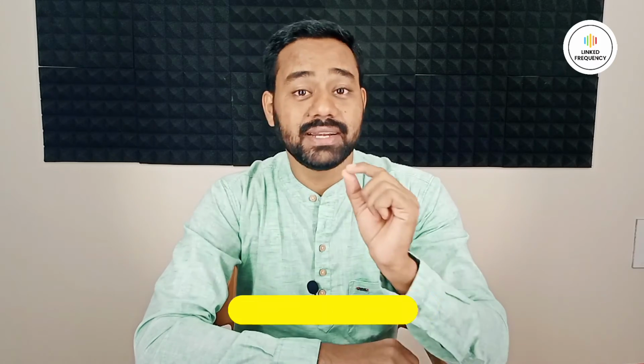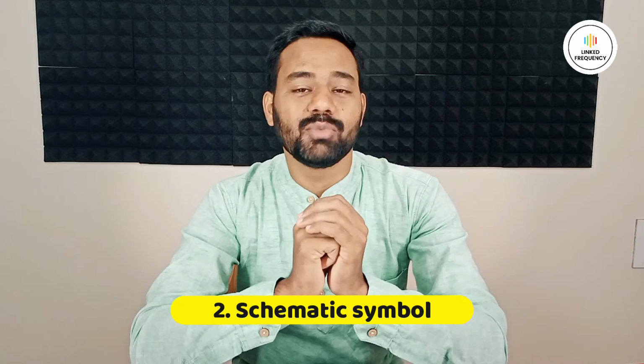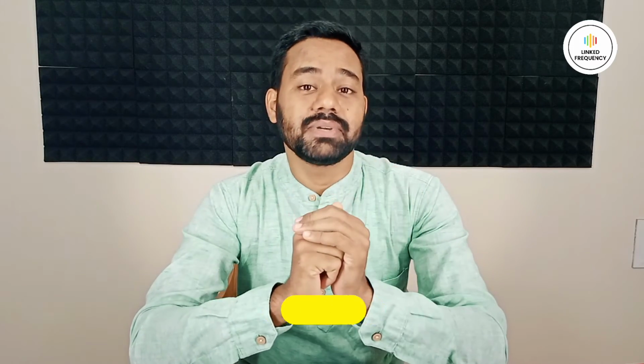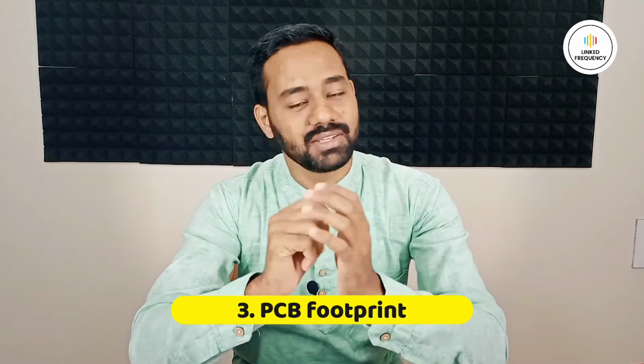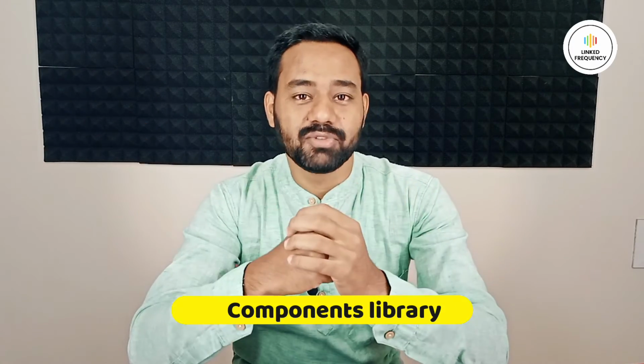There are 4 steps involved in this entire components library design activity. First one is identifying the right datasheet. Make sure that you download the datasheet from the authentic source, otherwise you will end up in a wrong direction. Second step is creating a schematic symbol using EasyEDA. Third step is creating a PCB footprint using EasyEDA. Both are different steps and done in a different wizard. The fourth step is all about combining schematic symbol and PCB footprint so that you can create a library which you can use for any project in the future scope.